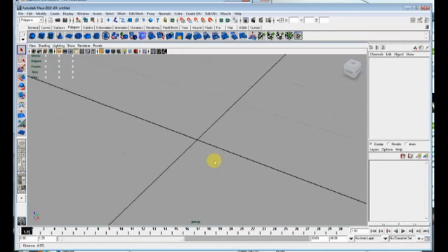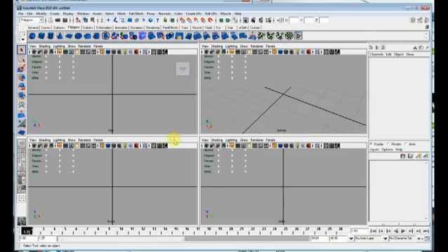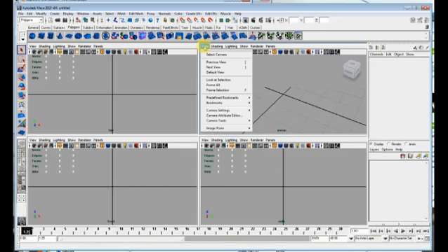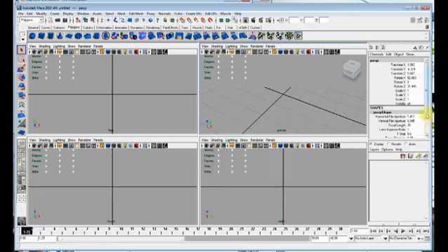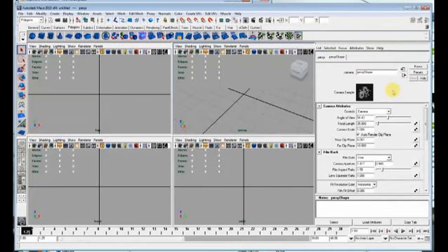Now here you're going to get an interesting situation where your clipping plane will wipe it out. And that is a function of the Maya cameras. So what you're going to have to do is go to your three views, top, front, and right hand side. And you go up to View and hit Select Camera. And this gives you the location of all your cameras. But again, you're going to hit the ever magic Control A key because you want to bring up the attributes.